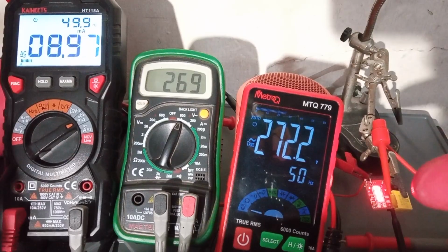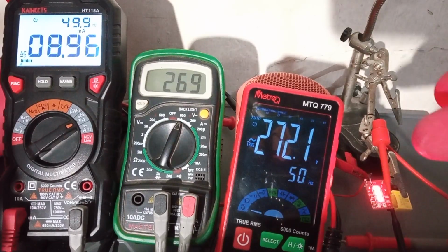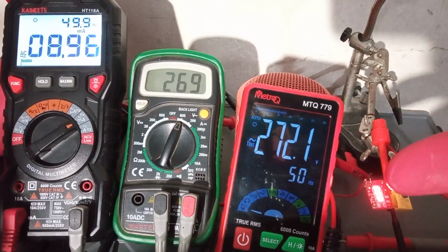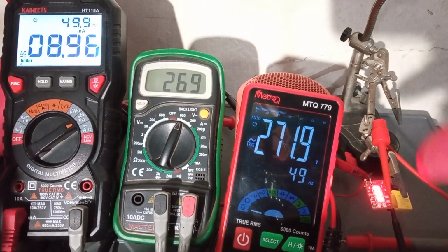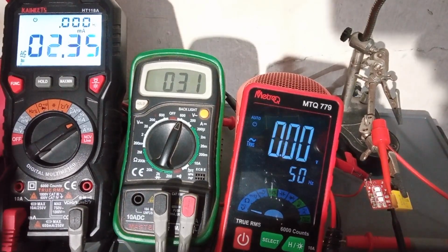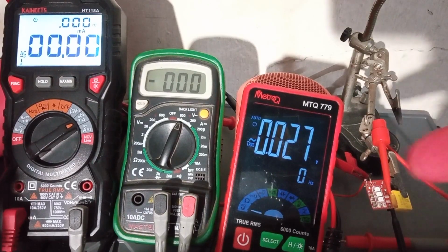And also make sure that you don't touch any of that circuit, because even though it looks like the LED glows and it is low voltage, it is not, because the capacitor is not isolating the AC voltage. Just to make sure, we are going to use around 500 volts AC. We will see what happens to this circuit.